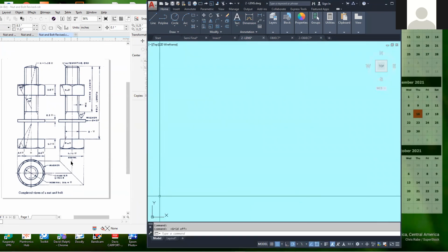We are going to draw a bolt M10. Now the first thing to do is to get the hexagon. In bolts, if you have a square bolt, in other words, if the top here is square and there are four sides, sometimes it'd be difficult to use in a small space because you're going to have to get a whole 90-degree turn to be able to move it. And if you have an eight-sided figure, it could be easily damaged or rounded off. So the most popular size that is used for bolts would be the six-sided figure, or hexagon.